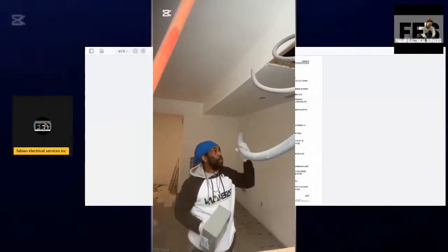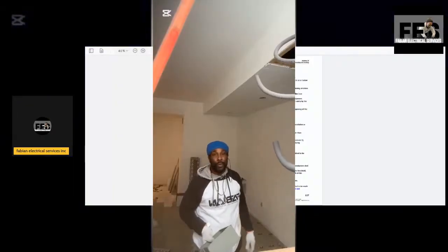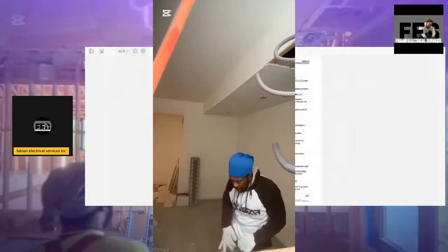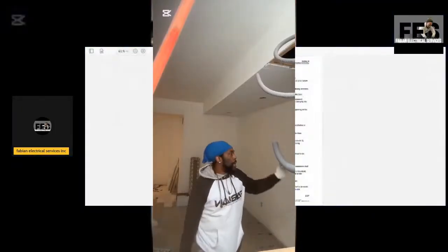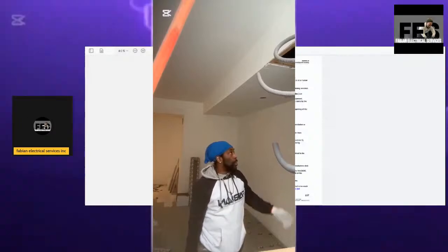And again, this is the 2-inch electrical PVC conduit. The trade name we normally use is Carlon. So this is a 2-inch pipe, and the other pipe that's above is a 3/4. That pipe is going to be for the high voltage line that's going to be going to the actual generator transfer switch. So now that you have seen the electrical conduit, this is the electrical conduit that I mentioned